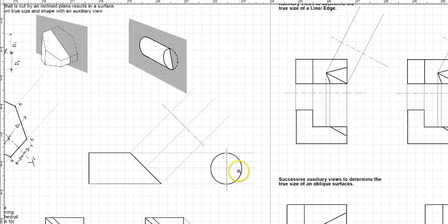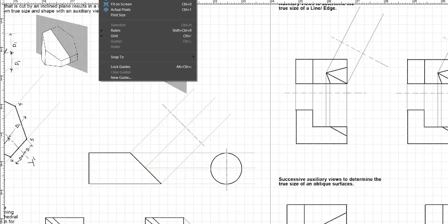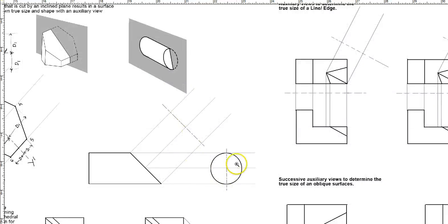So right now I have the top, bottom, and the center projected. So if I turn my lines off, it's going to be a lot clearer to visualize. So I have my reference lines going here from the front to the side view, and from the center I'm going to measure this distance and project it over here.